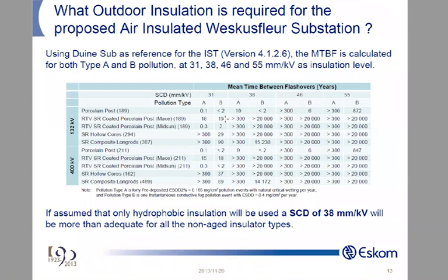Cool. Oh, but the coating won't last 18 years. We've got more than 20 years on coating in severe environments. But there are good coatings and there are poor coatings. Because with the other manufacturer's coating down here, you will be getting a flashover every 0.3 years, and for type B a flashover every 2 years. So, my goodness. You specify out there, I would like an RTV coating. It must be hydrophobic. And both of these tend to come back.